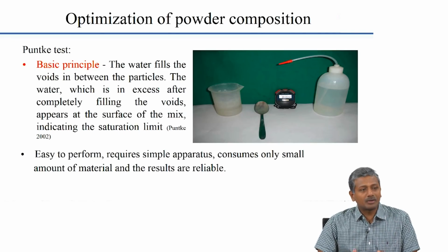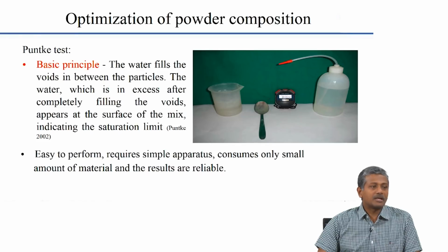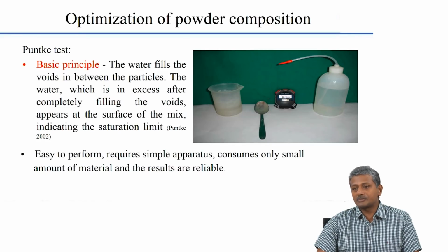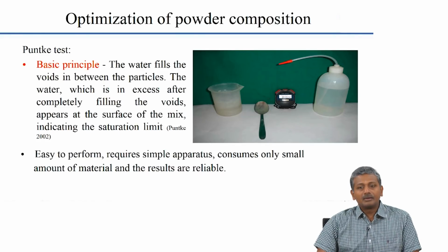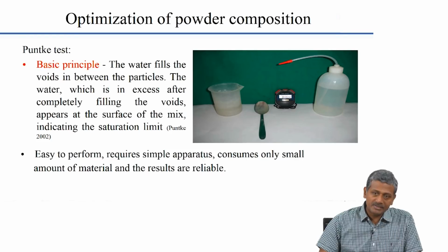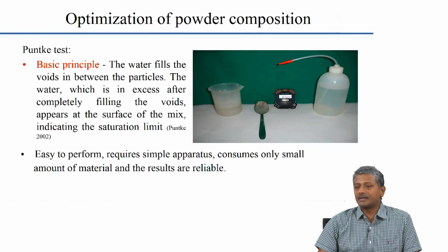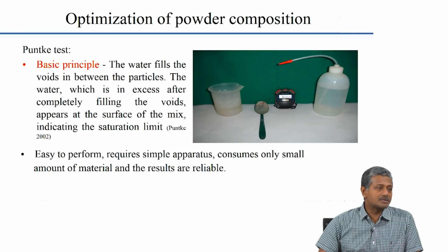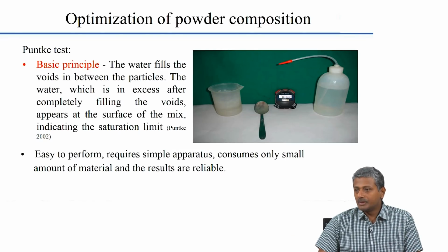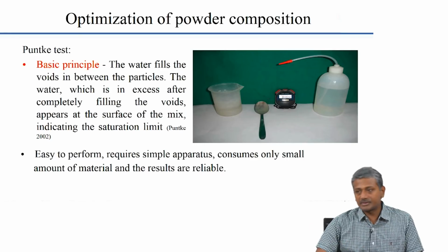But after you lay the concrete, what problems can you expect with the slab which you do not have with the column? You have a problem of plastic shrinkage. Yeah. Plastic shrinkage can be very large with the slab, especially if your flowability is high. How is the flowability maintained at a high level? Maybe you have a little bit extra water in it, maybe you have more super plasticizer in it. So, if you have more super plasticizer, what do you expect will happen at the setting time? Setting time will also increase, the concrete will now set much slower. So, the risk of plastic shrinkage goes up as the setting time of concrete keeps on increasing.